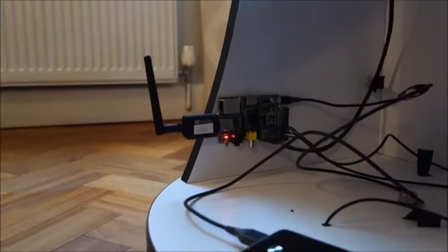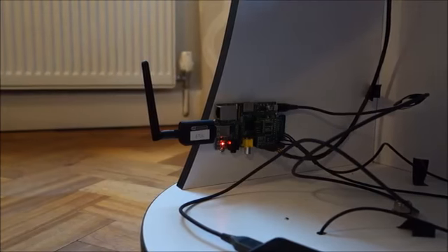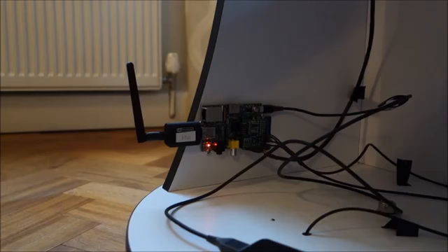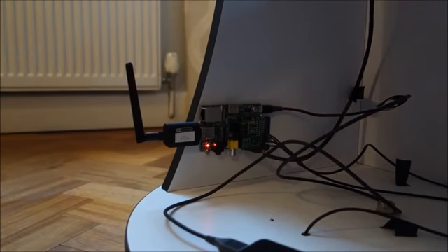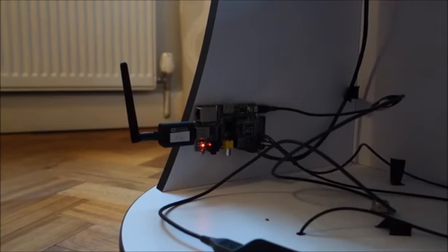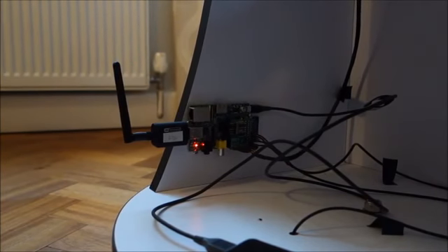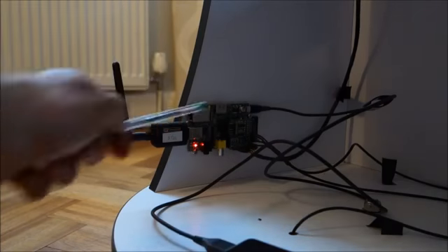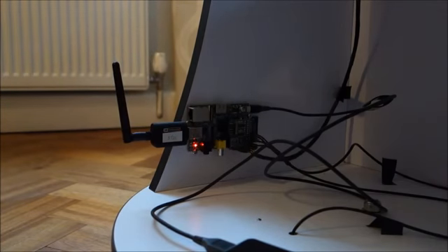The position sensors are then read by the Raspberry Pi, which, as I've already mentioned, replaces the Arduino which was used on the old design. There's a couple of reasons why I'm using the Raspberry Pi instead of the Arduino now. First one is the fidelity of the analog digital conversion. This board mounted on the Raspberry Pi is an ADC Pi breakout board which has a 17-bit analog digital converter, which means the precision of the angular measurement is higher using this.